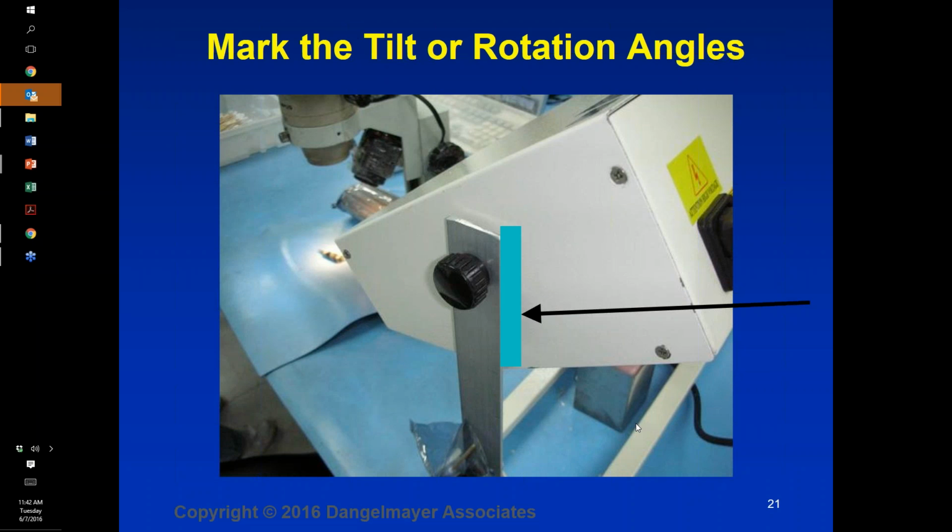Another good question, is there an easy way to tell the technology type of a given ionizer? Well, if you're making measurements on an ionizer and you have the instrumentation to make those measurements, you will be measuring the offset voltage. If you have an AC ionizer or a DC ionizer, you will find there may be a non-zero offset, even though it's a very low level. That'll indicate, first of all, that you're not dealing with a nuclear or X-ray type ionizer, because the offset voltage of those ionizers will always be zero.